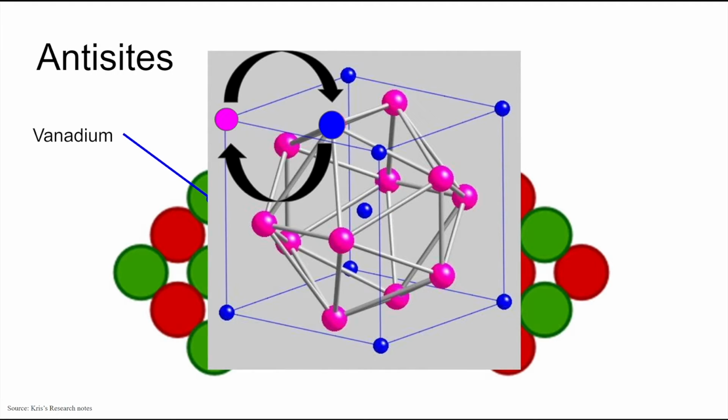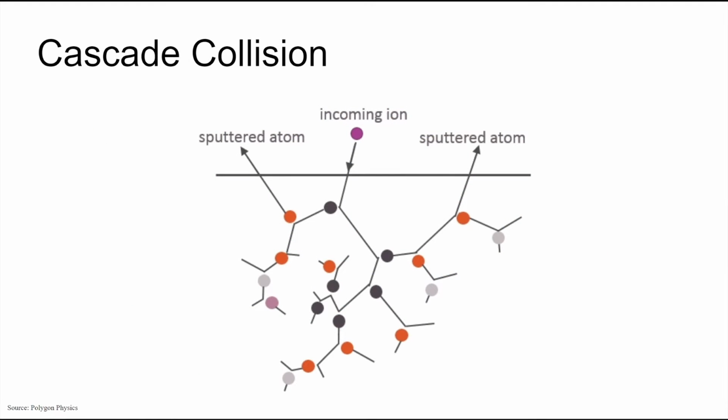In this metallic compound, the primary mode of mass transportation occurs through collision cascade or displacement cascade. Due to V3Si being an A15 compound, the high electron density increases the probability of these energetic collisions that are induced by an energetic particle. In the solid compound, an atom within the V3Si compound is displaced by an incident damaging particle, which causes additional displacement, similar to the butterfly effect.